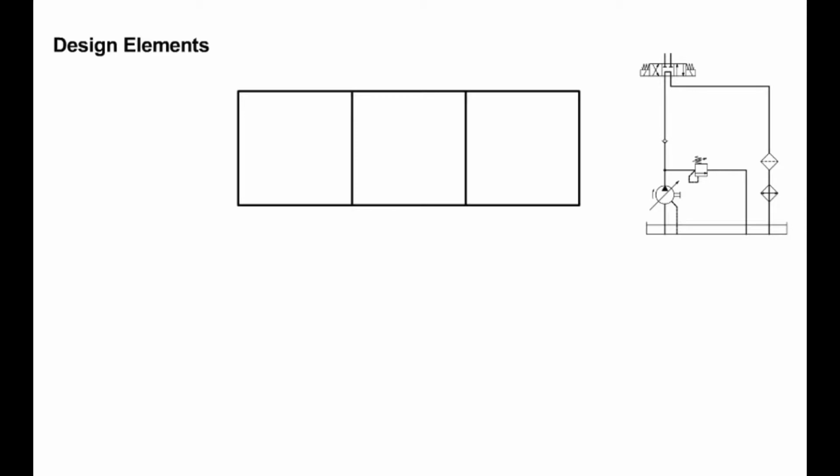In order to control the flow, additional valves must be used. Valves used to start, stop, or change the direction of flow in hydraulic systems are known as directional control valves. You have already become familiar with the square as the functional symbol to represent a valve. The symbol for a directional control valve is made up of a number of squares. Each square in the symbol stands for a possible spool position. As you can see from the diagram, the directional control valve shown has 3 spool positions.